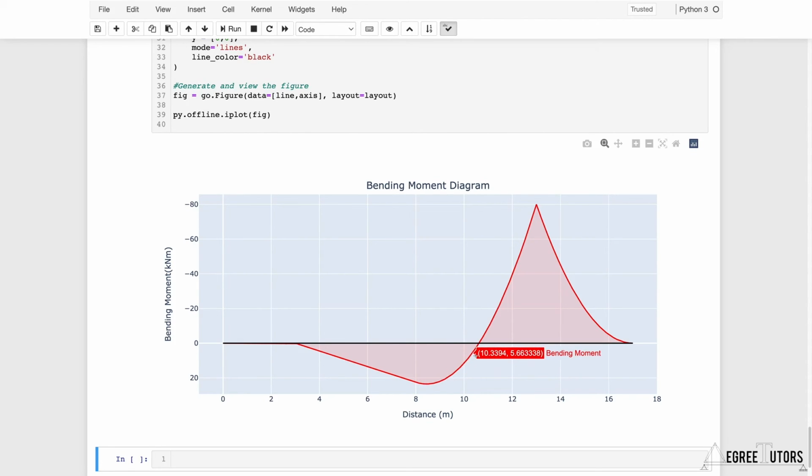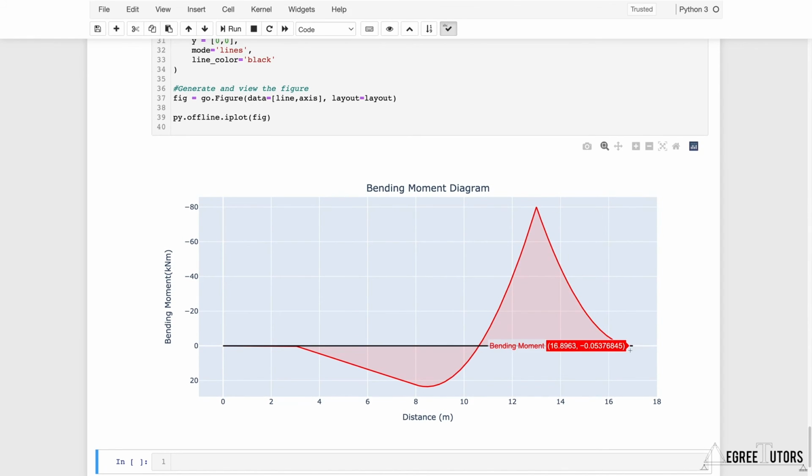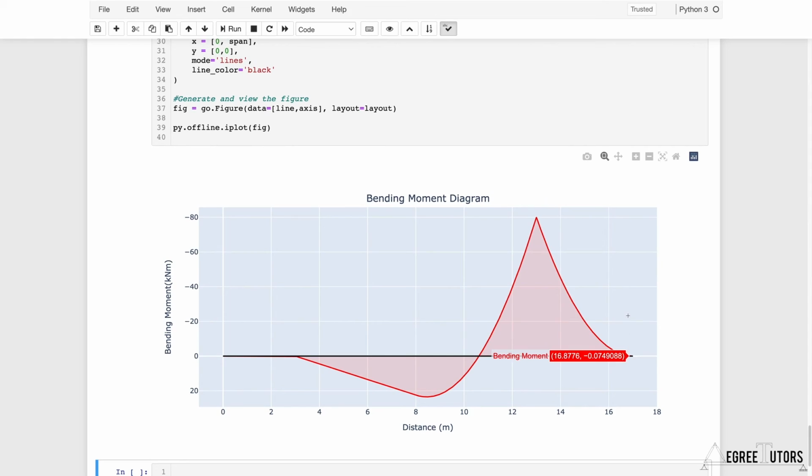And again, emphasizing here that the bending moment diagram is positive downwards, and so a negative slope does indeed point the line back up this way. So we have a negative slope, until we get to this point here. And remember, we said there was going to be a peak in our bending moment diagram where the slope changed from being a negative slope to a positive slope. And sure enough, after that peak, we have a positive sloping bending moment diagram all the way down to 0. So down to 0 here at the free end, which is what we would expect. So there you have it. We have our bending moment diagram and our shear force diagram.